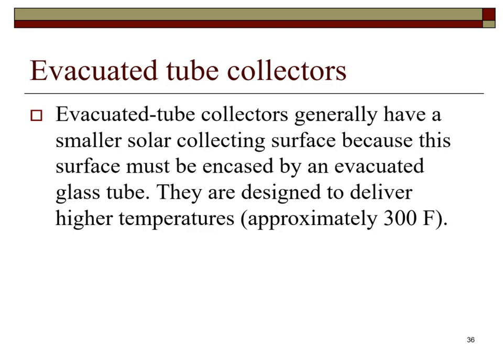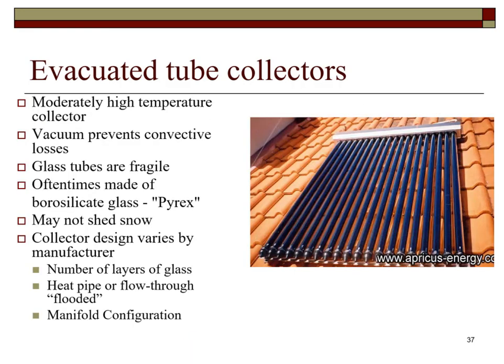As stated, the evacuated tube collectors deliver higher temperatures but do not have the same efficiency with respect to gross area due to the empty space between the tubes and the vacuum space between the outer tube and the absorber. Evacuated tubes have the disadvantage of being fragile.